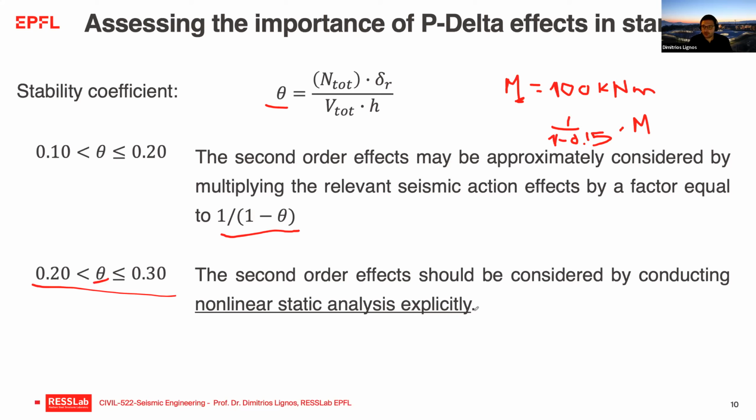In order to be able to do this, you will first have to take a nonlinear analysis class next semester, so that you can do the nonlinear static analysis explicitly by writing the equations of equilibrium for the entire frame structure under the deformed configuration. In that case, you will be able to explicitly measure the effect of P-delta on the member forces.